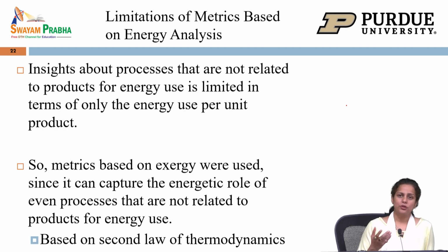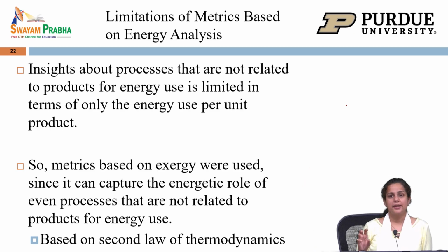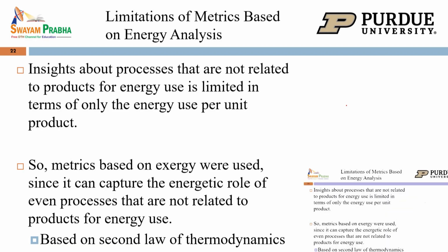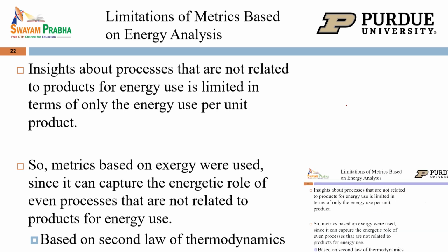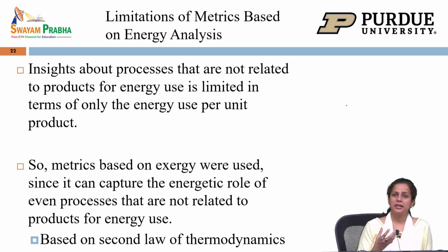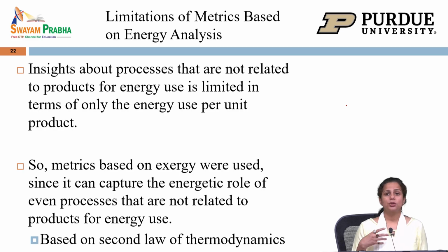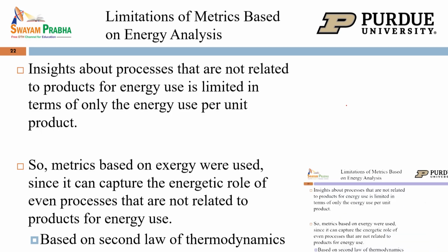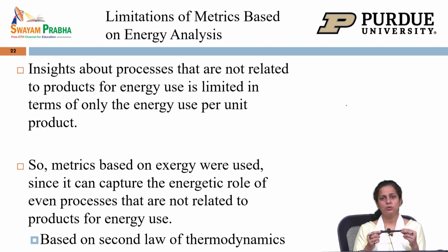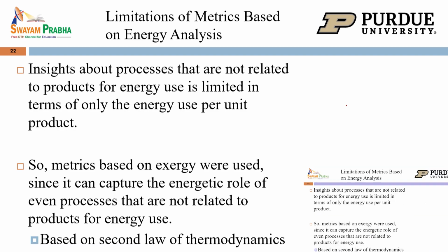So, in that case, what we do is we move from the first law of thermodynamics to the second law of thermodynamics, and instead of just looking at the fuel value, we also start looking at the exergy flow, which captures the energetic role of even processes that are not for products for energy use. So, any product, let us say a pen we are holding, a pen will have some exergy. It will depend on the process that was used to make that pen. So, even though our pen does not have a fuel value, we can use a similar kind of thermodynamic analysis to test the sustainability of the process.